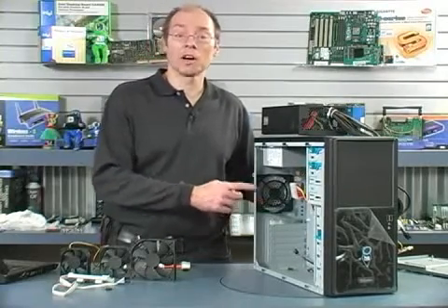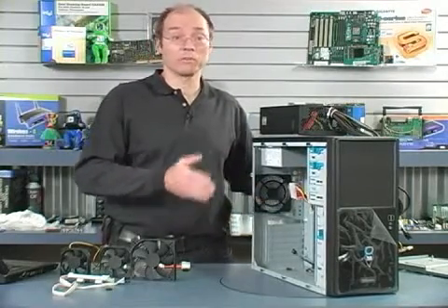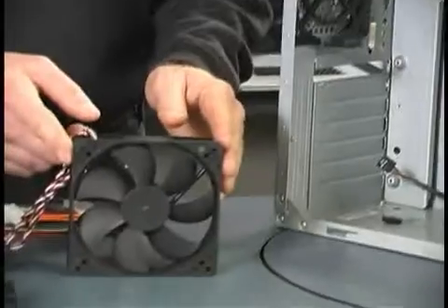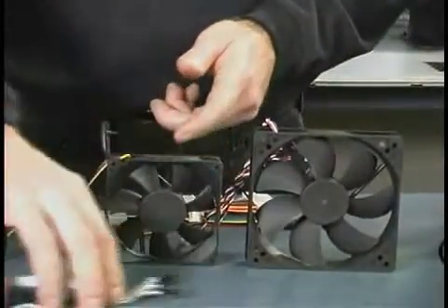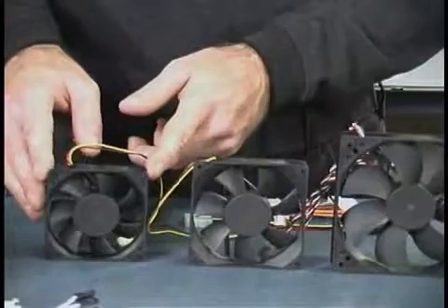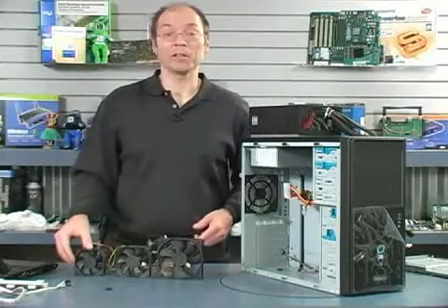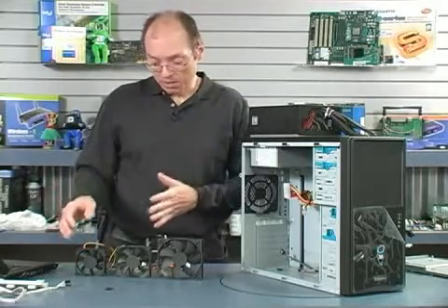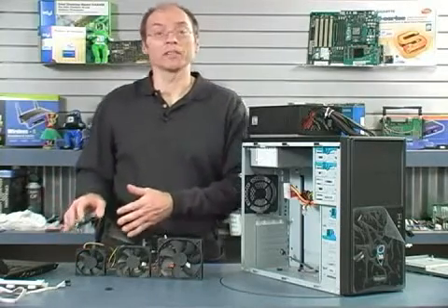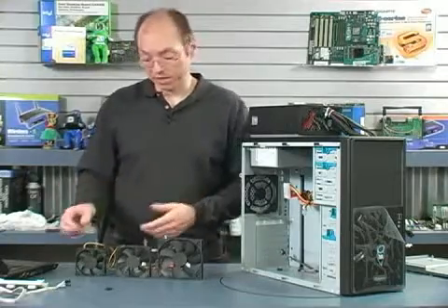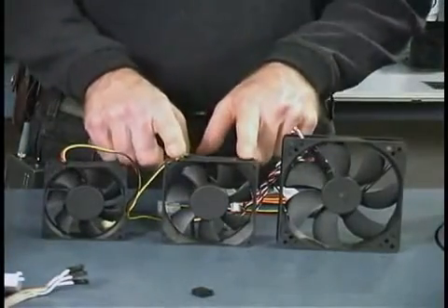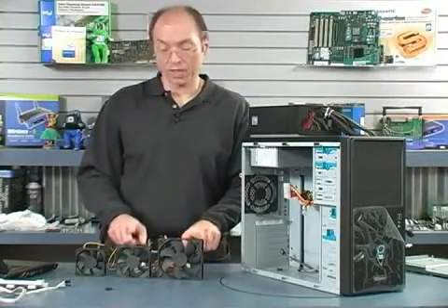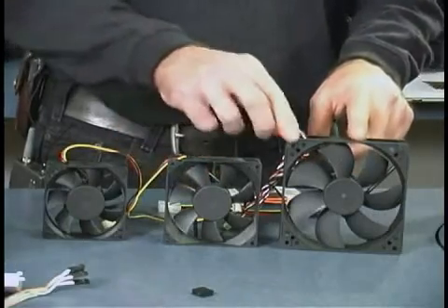Now, cooling fans come in 3 main sizes as far as desktop PC cases are concerned. We have a 120 millimeter, we have a 92 millimeter, and we have an 80 millimeter. Years ago, cases used to come with a single 80 millimeter fan in the back. That proved to be not enough, plus the fact that smaller fans tend to make more noise. So, in the interest of having both more airflow and quieter PCs, we generally went to 92 millimeter fans or even 120 millimeter fans in the back. I generally won't buy a case unless it has either a 120 or a 92 millimeter rear chassis fan, preferably the 120.